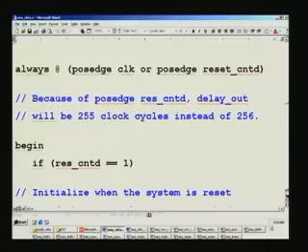I'll modify my question. Yeah. To sense any change in the waveform. See, for example, you just sense the change in that. Right. How do you go about it? Is this the way? Where previously you set it as 0 and then you check if it's 1. Yes, my question, answer still is valid for that. What all I answered. So we are sensing the level, but taking a decision only at the next clock pulse, because we don't have means of doing it without violating the RTL coding guidelines, right.